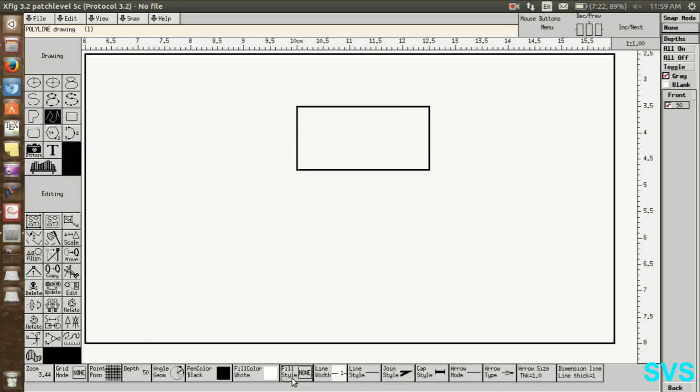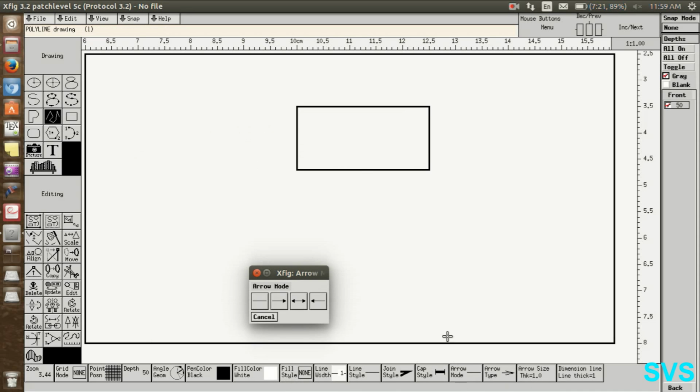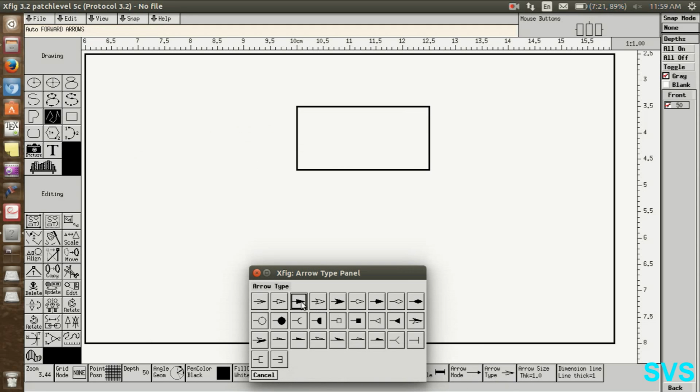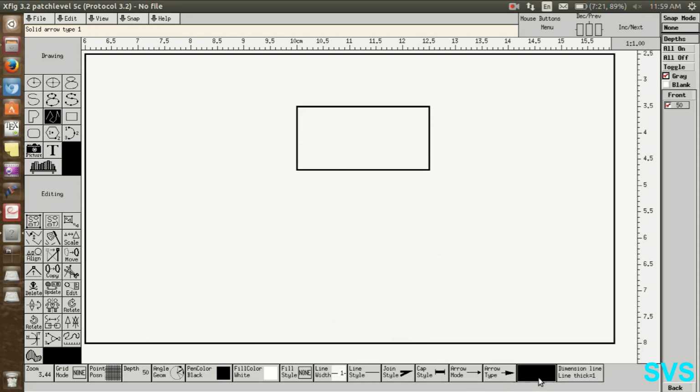So we'll be setting the arrowhead. There you go. So we'll select the arrow mode, and the choice of arrow, which we can have filled. Similarly, we can have thickness also. So we are using snaps, and that mouse guider is guiding how to use it.